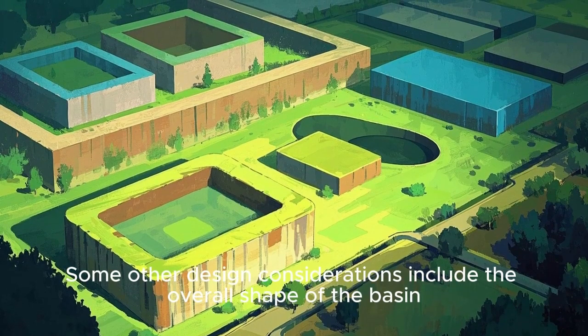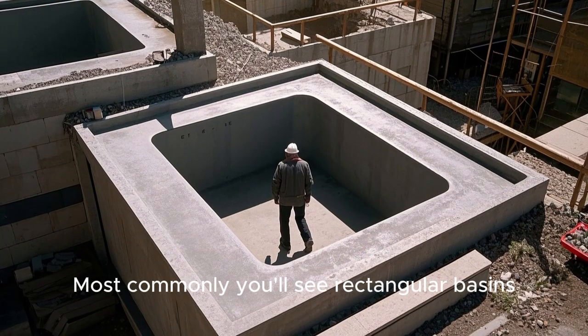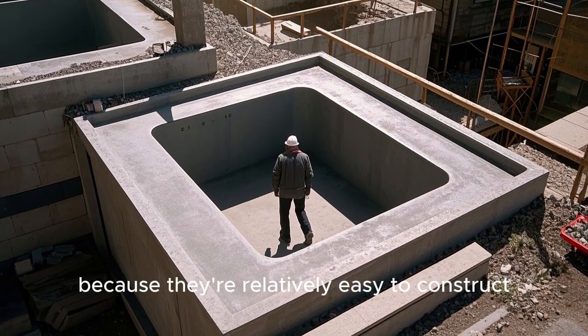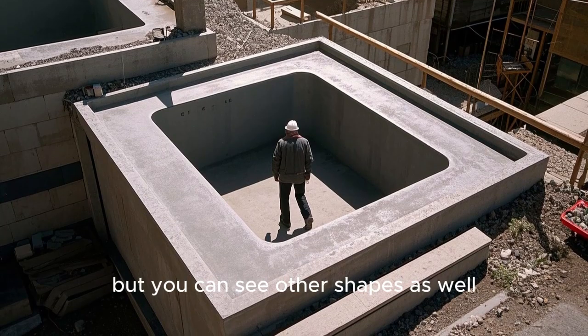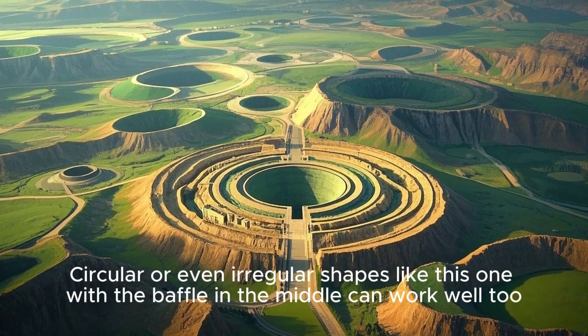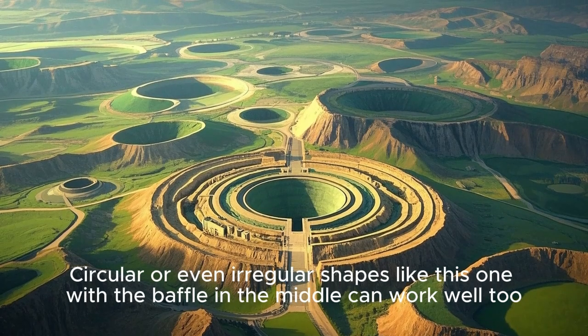Some other design considerations include the overall shape of the basin. Most commonly, you'll see rectangular basins because they're relatively easy to construct, but you can see other shapes as well. Circular or even irregular shapes like this one with the baffle in the middle can work well too.